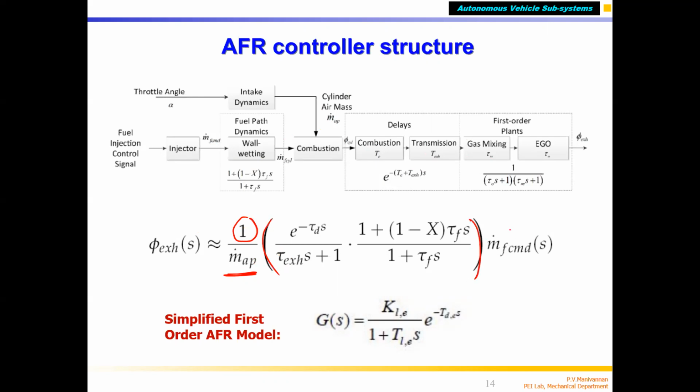Here you are injecting fuel at the inlet port. We know that some amount of fuel sticks as a fuel puddle, for example 10%, and the remaining 90% goes in. The fuel puddle also evaporates. That is called evaporation dynamics. If the fuel injected is 1 milligram, how much goes inside is decided by this equation. This depends upon the evaporation time. Tau F is the fuel puddle evaporation rate. Again, this is dynamics, with time delays and exhaust dynamics.